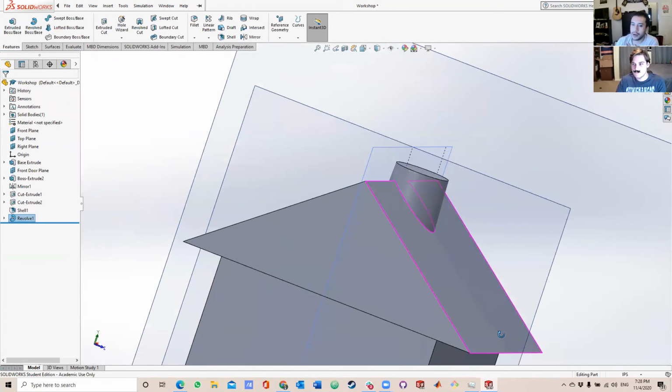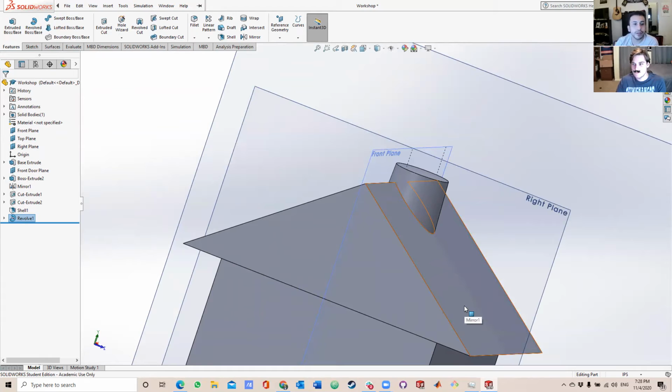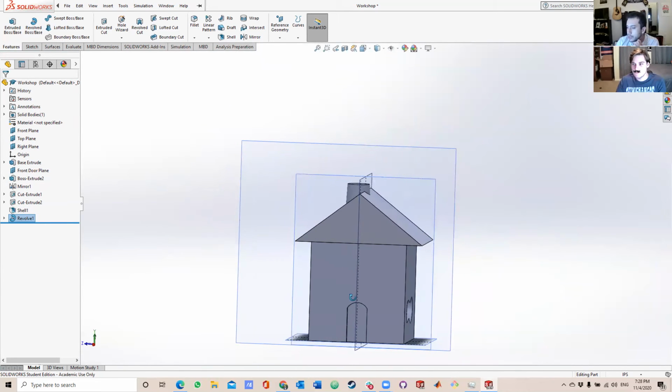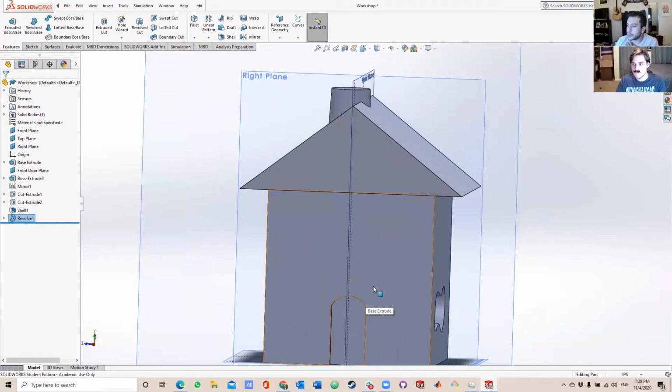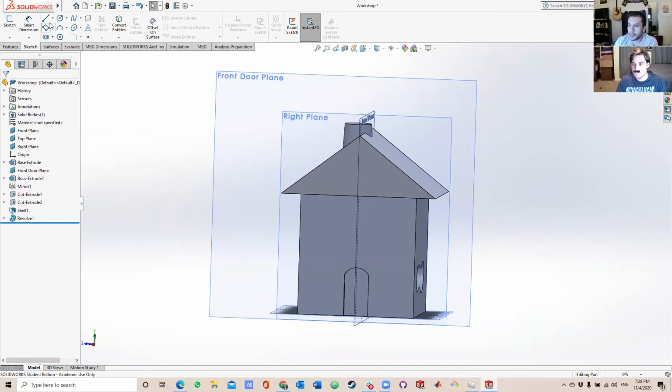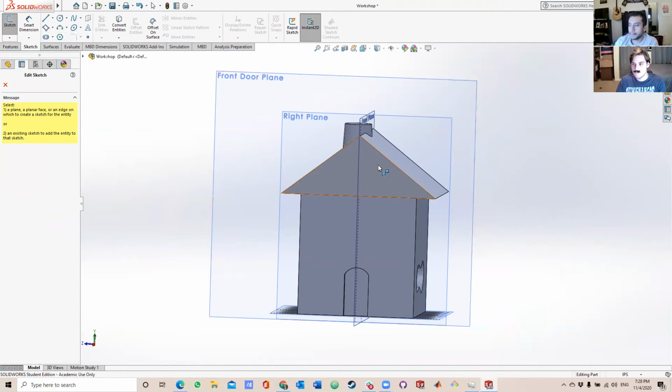And the same thing works for cuts in the same exact way. That area that would have become something if we selected extruded cut would just cut around it. We just cut that same piece. So here is our little tiny house. Another thing that we can do when we're trying to make our designs symmetrical, a great tool that we can use is this center line.